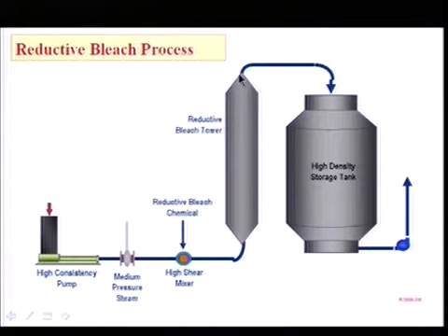All the chemicals are in, so you can drop from top to bottom. You do not have to worry about air taking away your chemical, because the chemicals are already in the fiber. There you store at high consistency 10 to 12%, and then dilute at the bottom with the white water and pump it to your paper machine for making bright, nice paper.